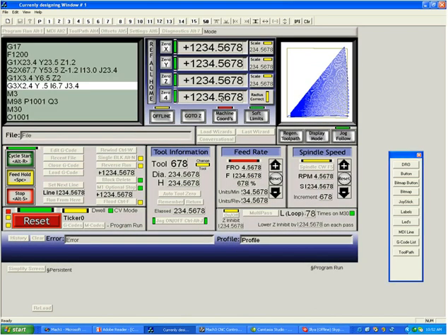As our example in this case, we're going to write a quick script which handles a tool change. We're going to take an M6 command, and we're going to break that M6 command into an actual Visual Basic script to make your program do what you want it to do in a tool change. The reason I picked tool change is that most people want something different to happen on a tool change. There is no one job does all thing which can be done to a tool change. So let's take a look at how we would do that.